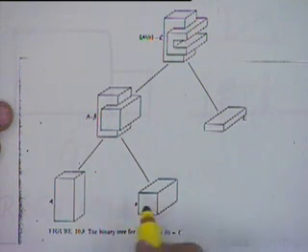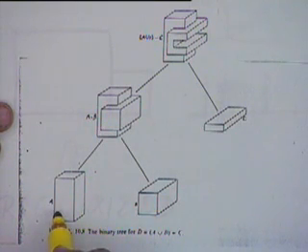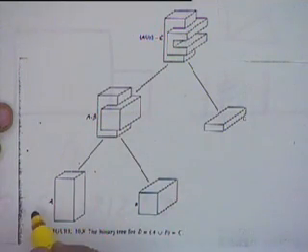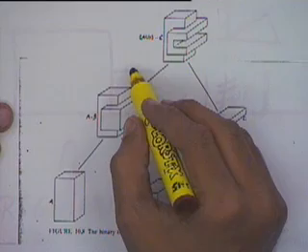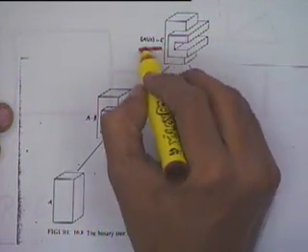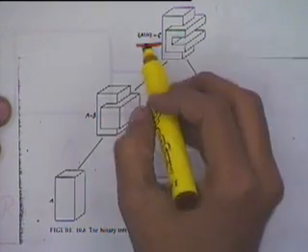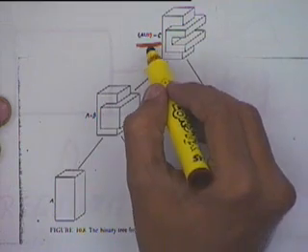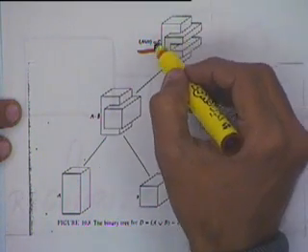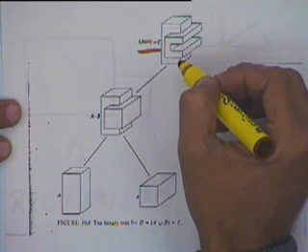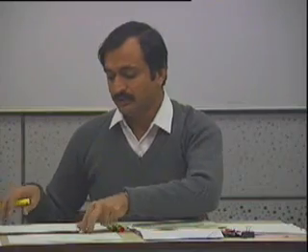The other thing I mentioned last time, that if I have an object being made like this, these objects are essentially primitives. They are transformations of a cube, but this object is not a primitive. So if I want to get some properties of this object, I cannot just use the binary expression given over here, A union B minus C. I have to evaluate this expression, get a graph representation of this, or get the information on the surfaces which constitute this body, and only then I can use this. Again, that process I mentioned was a process of evaluation.